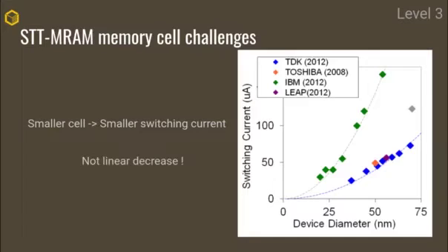So if I use the gained area and pack as many cells as I used to in this smaller area, say I used to be able to pack 8 cells and now I can pack 32 cells, then the power density would actually increase because this decrease is not linear. And so I now have to manage a bigger heating issue and a bigger power consumption issue per area.